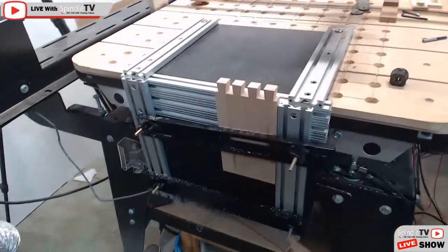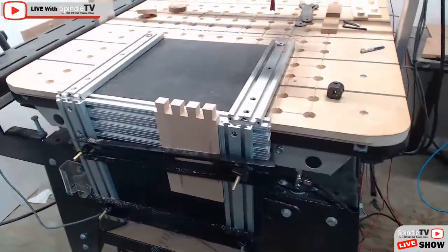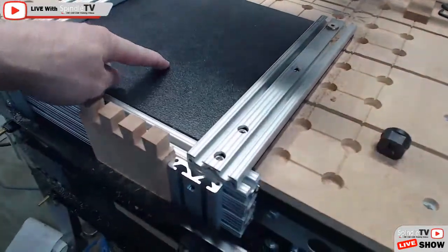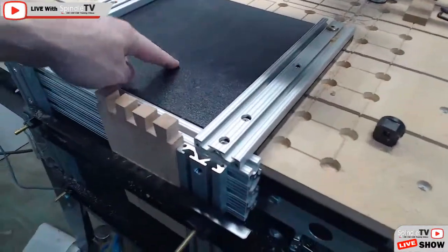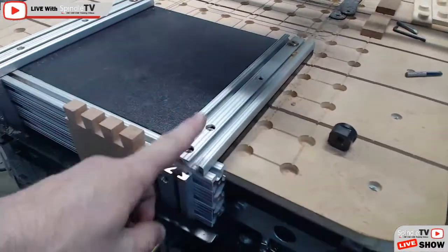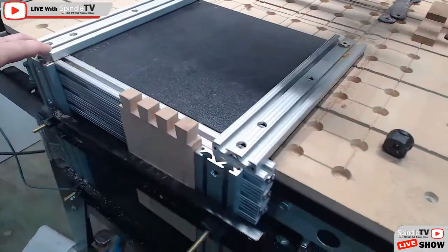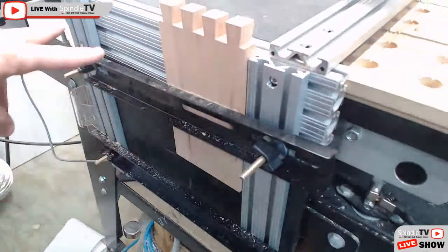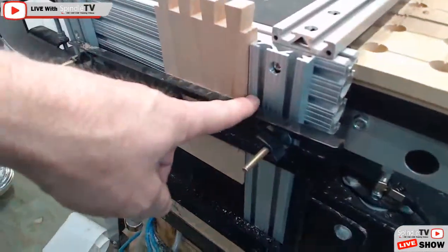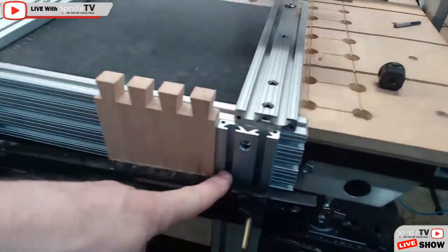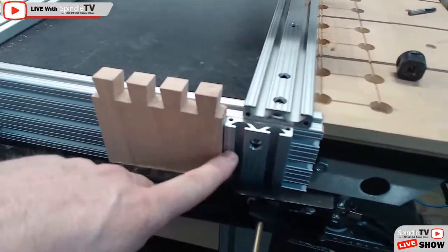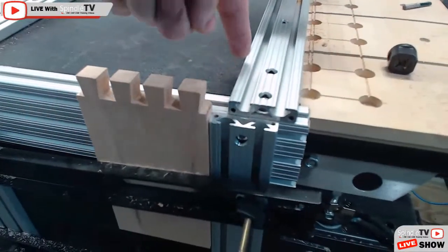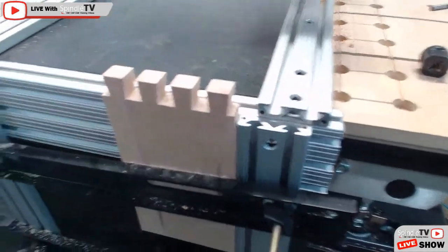All right, so this is the joint making jig. The jig is made up of 1/2-inch HDPE polyethylene. We've got some 80/20 tracks on the side, the front faceplate also, and the 2 side fences. This fence is adjustable, and if you'll notice here, I've got this fence currently offset from this fence, so my dovetail bit, when it cuts, will be able to clear this fence and everything.